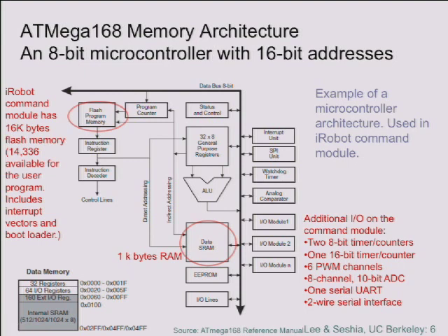Yeah. There are memory maps, so the other stuff are memory maps and other locations. Yeah, so the key thing here is that you've got to understand how memory addresses get mapped into physical devices in memory. If you're programming at the bare iron level, you have to understand that. You can't get away with ignoring how memory addresses work. And that's one of the key properties of controlling the hardware: understanding what a memory address means on this particular implementation of the hardware.